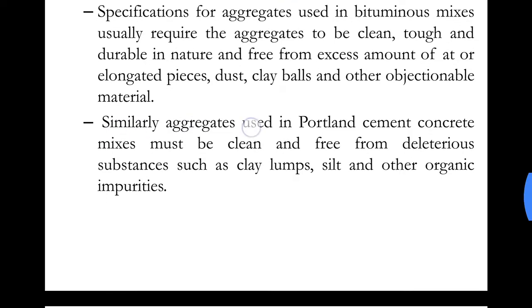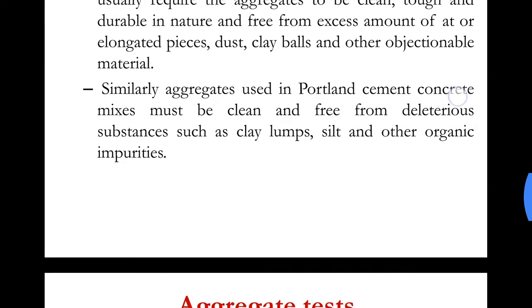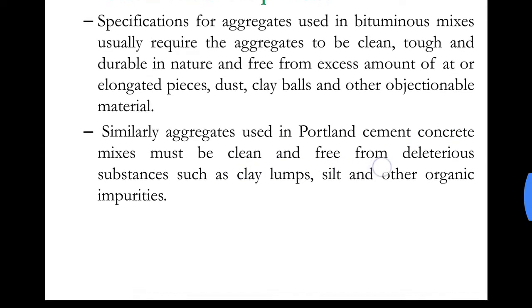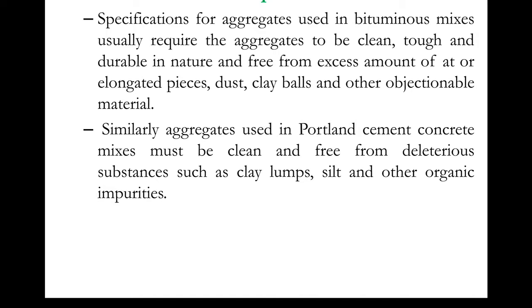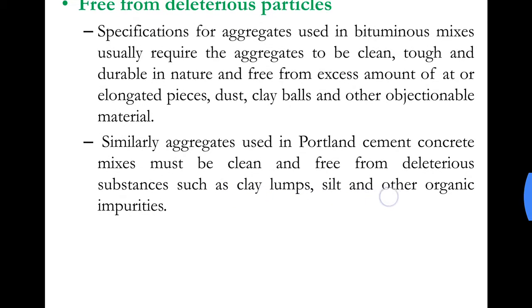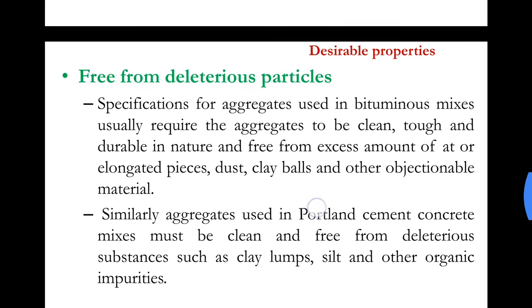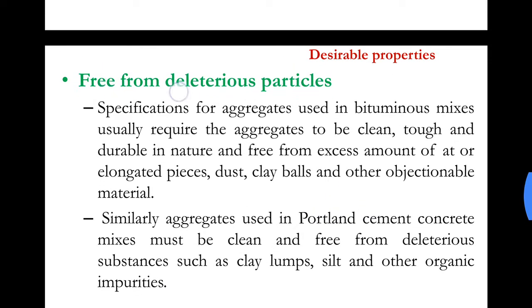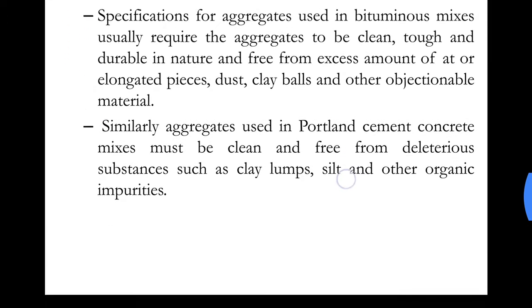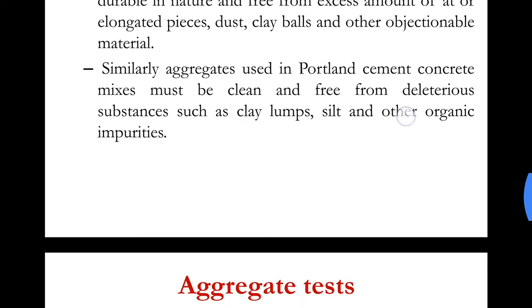Similarly, aggregates used in Portland cement concrete mixes must be clean and free from deleterious substances such as clay lumps, silt, and other organic impurities. So this is free from deleterious particles. The aggregate sample should be free from all these types of foreign matter.